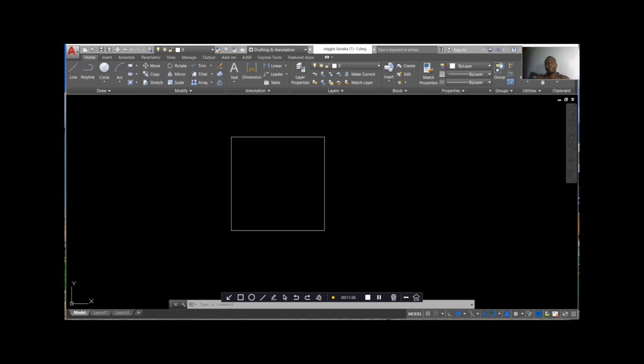Okay. So we now trim the walls to 230. We now offset the walls with a 230 offset distance. I'm clicking offset, and on my command line it always writes what I've clicked, and then it tells me what I'm supposed to do next. Offset is what I've clicked.